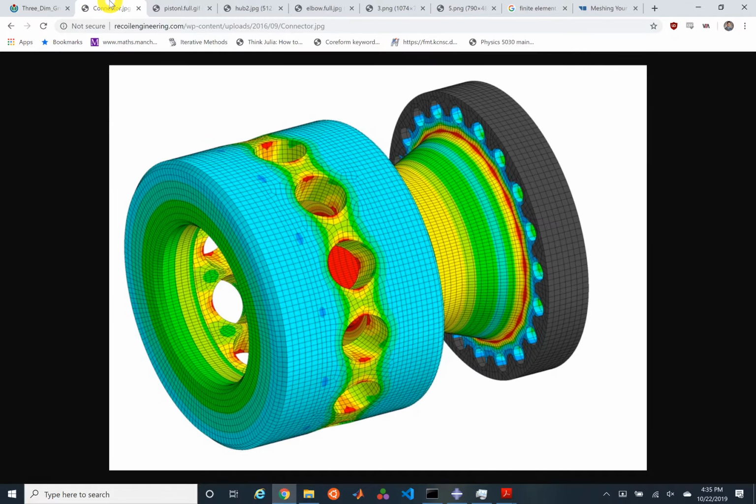But as I mentioned, typically we're trying to construct these hexahedral meshes. As you can see, they tend to have flow along surfaces and tend to be fairly orthogonal to these surfaces. They also just tend to look beautiful. And we'll see that some of the quantitative metrics we use for element quality tend to be things that, for whatever reason, aesthetically seem to look kind of nice.